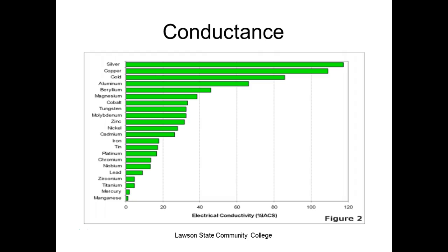This even happens sometimes in your wall outlets. They'll have a wall outlet that's been going on for a long time, and all of a sudden, wall outlets, guys, are not supposed to get hot, right? You understand? If it gets hot, what does that mean? It means there's an R in there, right? That's not supposed to be there. So to get heat, we've got to have an R.